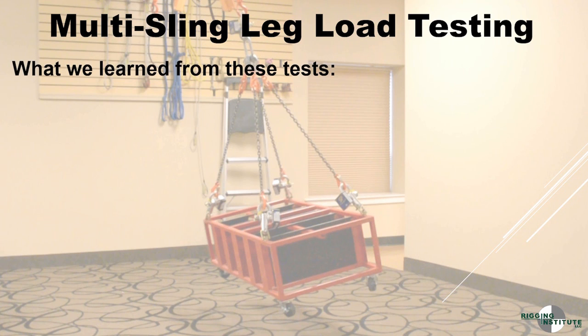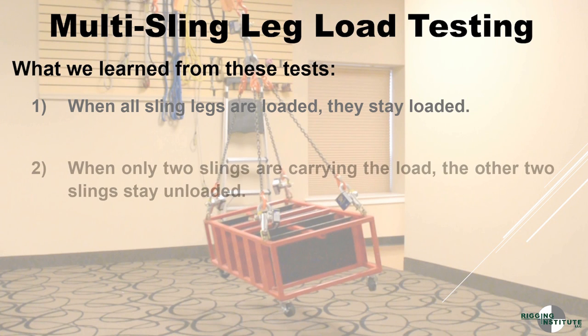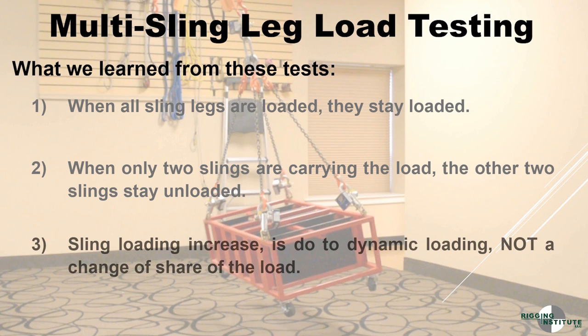What we learned from these tests. When all sling legs are loaded, they stay loaded. When only 2 slings are carrying the load, the other 2 slings stay unloaded. Sling loading increase is due to dynamic load, not share of load.